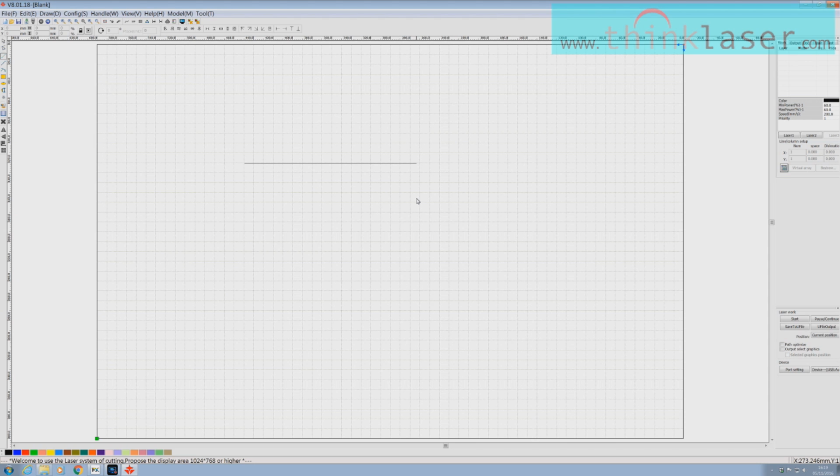I now need to keep the control key held down and click the mouse button again, and that now locks the line in place. Now that line, if I put a marquee round it or touch the line, you'll see that it's got handles on it. It's got a center point, which is its position point. If you remember, we spoke about position in the last session, and what we've now done, we've looked here and we've still got center position selected. So that's where the definition of the line comes from.